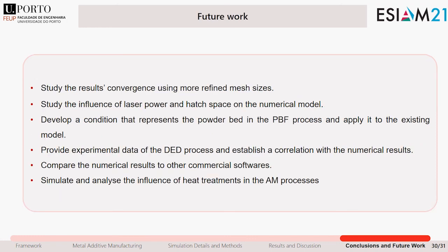As future work, we recommend to study the results convergence using more refined mesh sizes, study the influence of laser power and edge space on the numerical model, develop a condition that represents the powder bed in the powder bed fusion process and apply it to the existing model, provide experimental data of the direct energy deposition process and establish a correlation with the numerical results. Compare the numerical results to other commercial software, and finally simulate and analyze the influence of each treatment in the additive manufacturing processes.